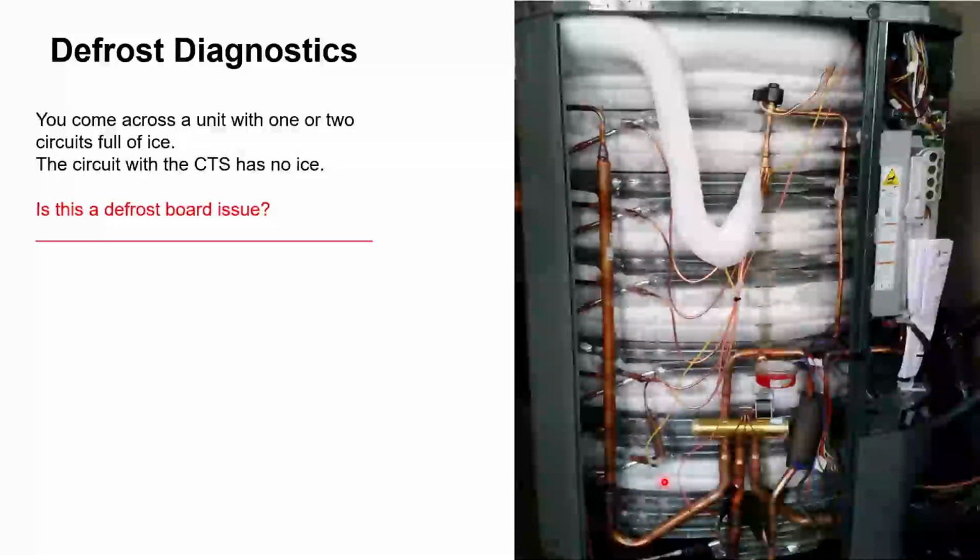In those areas that I mentioned, the problem is the fog will settle in for 3, 4, 6 weeks at a time. And so we have a unit that looks like this for 6 weeks, and it's fairly inefficient. And so we will have to cut that J2 jumper to increase that termination temp on that coil temp sensor so that we completely clear this coil.